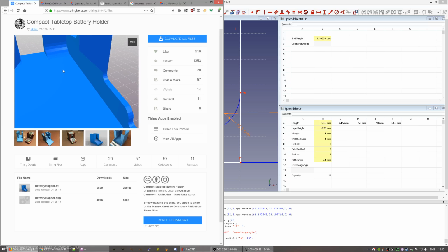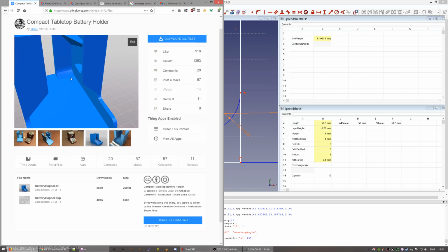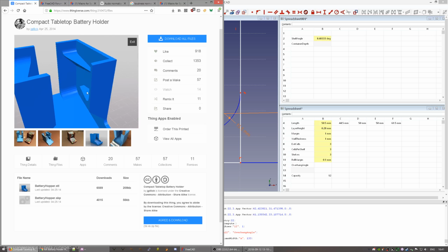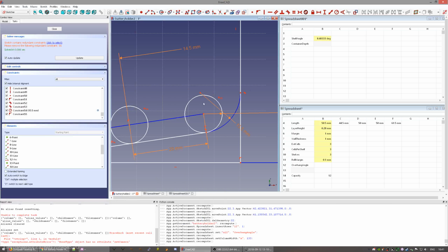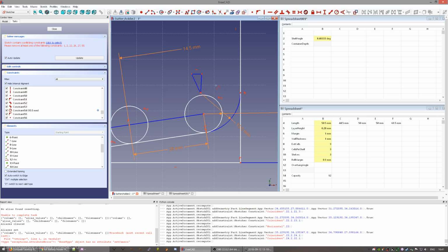And in this model, the only overhangs are under these shelves. So since we've been working on the bottom shelf, we haven't encountered any overhangs before this. But now I want to make the second shelf. Or at least I want to find out a few parameters about the second shelf. And this is when I am going to just design things that aren't in this plane, really. Conflicting constraints, where are those?